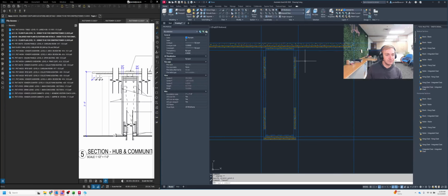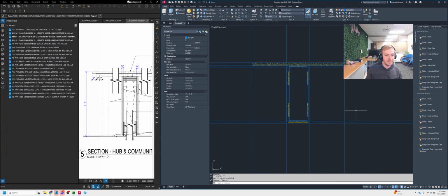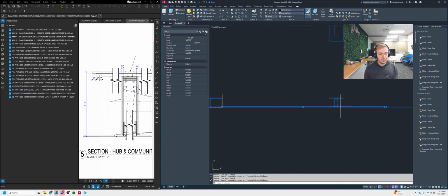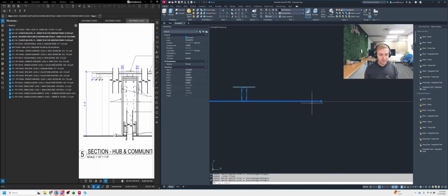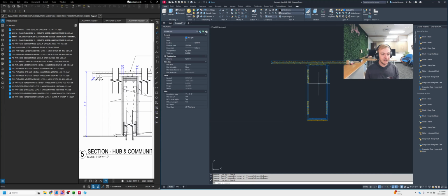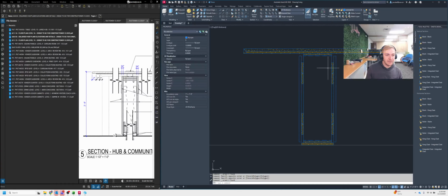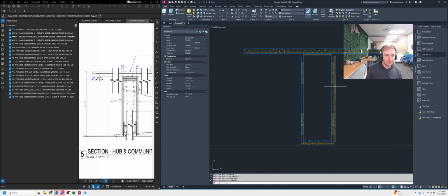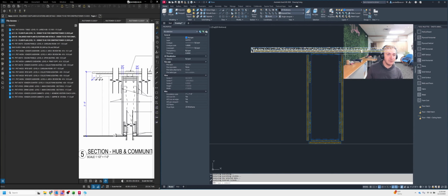All right, now we got all of that. We can start to remove some of these lines because they're not even needed anymore. Those go away. These can go away. In fact, these can go away, but I'm careful not to delete my grid by mistake, so I'm unchecking that. And then my panels here, I'm going to hatch those appropriately. So I'm going to go back to my annotation tab, grab my MDF vertical hatch, and drop those in those panels there. Okay, so then the last things we need are the reveals and then the outlets, detail work.